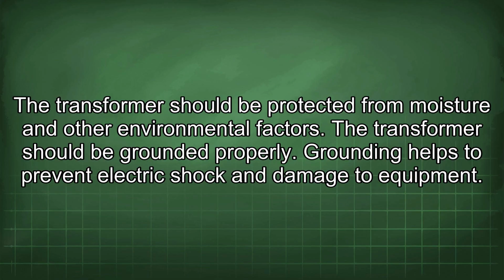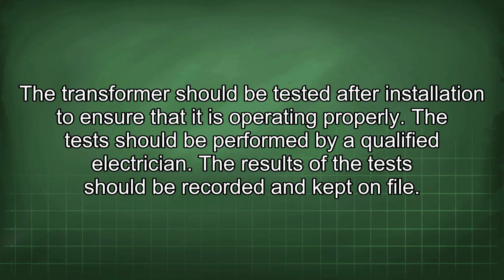The transformer should be grounded properly. Grounding helps to prevent electric shock and damage to equipment. The transformer should be tested after installation to ensure that it is operating properly. The test should be performed by a qualified electrician. The results of the test should be recorded and kept on file.